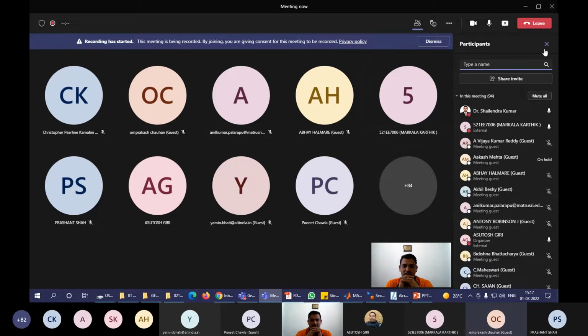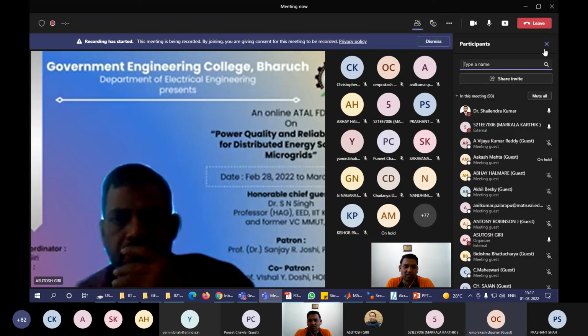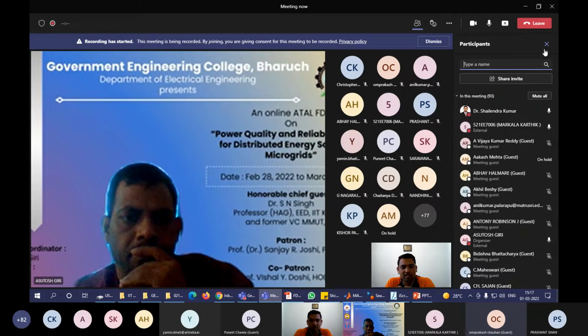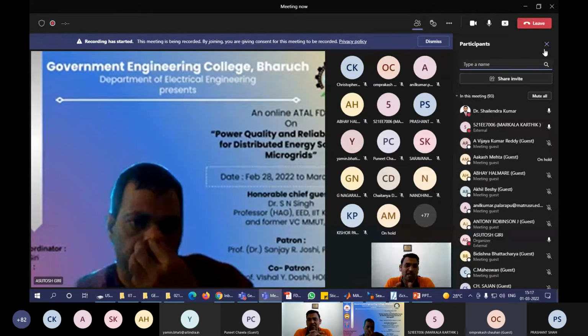Immediately you can go to the X by R ratio. It must be between 7 to 15, not more than that, and not less than that. But that condition we are not considering here. We are going for the ideal grid. So for the R value you can select, if I am not wrong, 0.01, and 0.4 millihenry you can consider for the inductor value. So you will get the ideal grid, and you will have a good THD in grid voltage. If you are intentionally creating disturbance toward the grid side, then you have to increase the inductor value.